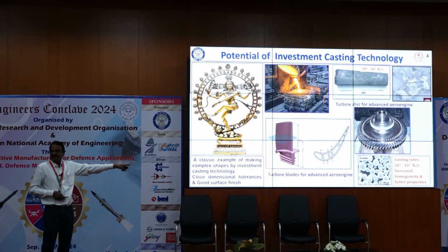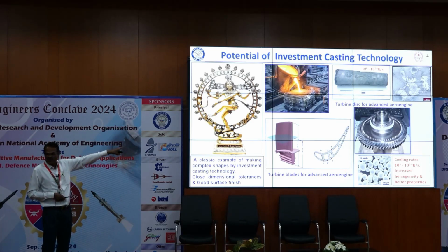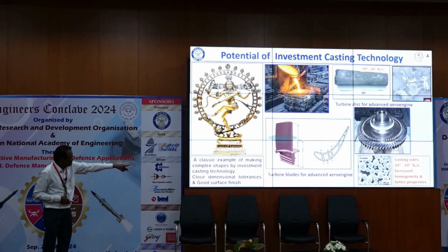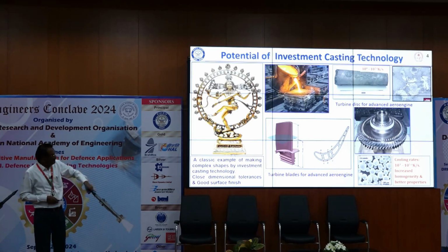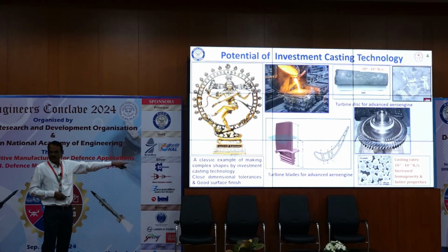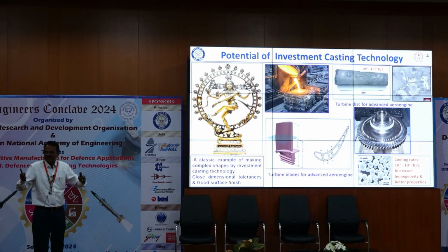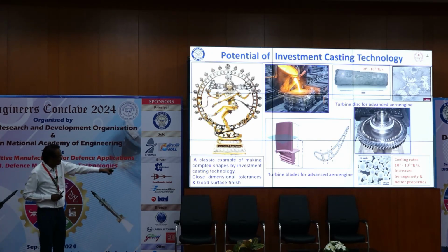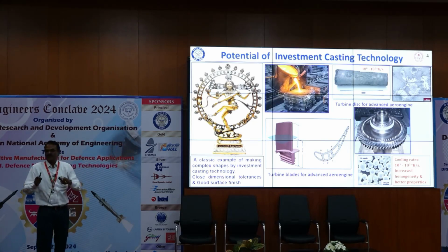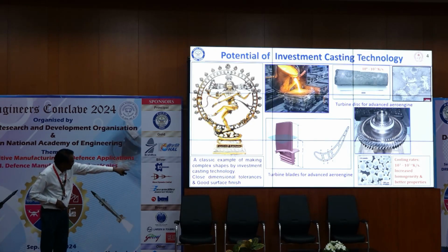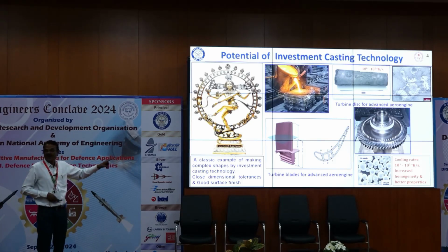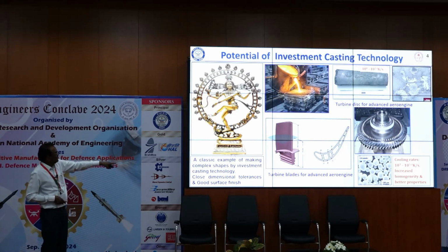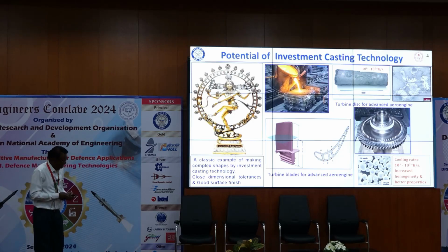Therefore, powder metallurgy, fine powders are very, very important. Why are they very important? See the cooling rates: 1 to 100 degree K per second in casting, as compared to a fine powder particle which is produced by atomization or plasma rotating electrode process, or any other techniques of similar kind, they will give 1000 to 1 lakh degree Kelvin per second. So the cooling rates are substantially high. With any number of elements, you will be able to overcome the segregation problem. The fine powder represents a large-size ingot, but the size is small and the composition is highly homogeneous. You will end up with a homogeneous microstructure, consistent mechanical properties with excellent workability. So that is the advantage of powder metallurgy, powders. Therefore, we are talking today about how to make the powders, high quality powders and all that.